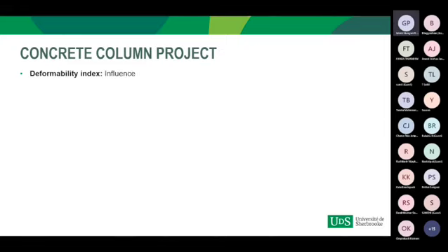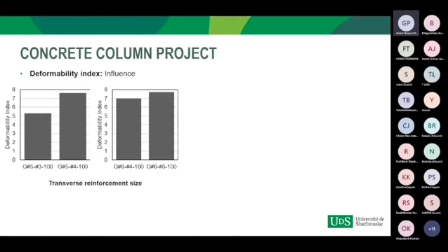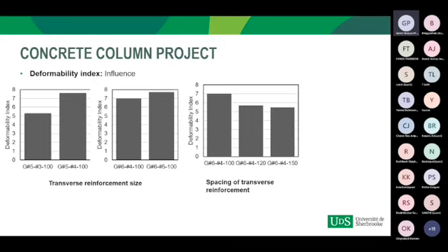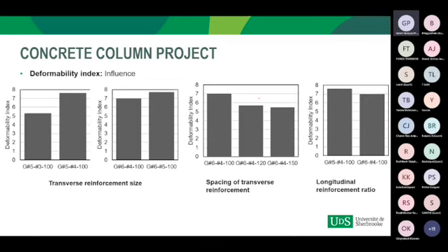The influence of the deformability index on the studied parameters was as follows: increasing the transverse reinforcement size increased the deformability index, and it was found that the lower spacing of the transverse reinforcement improved the deformability index, and increasing the longitudinal reinforcement ratio decreased the deformability index.